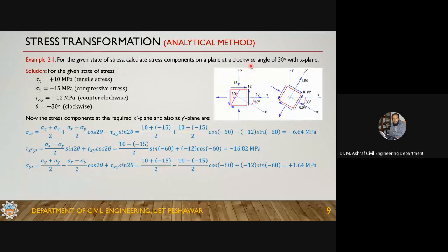So this transformation is also based on the elastic body. It's good you asked this question. There is no such independent assumption for this one, but the only assumption is that the body is elastic, isotropic, homogeneous. Okay, so these are the cases. Homogeneity may not be a requirement, but elastic and isotropy is the requirement.